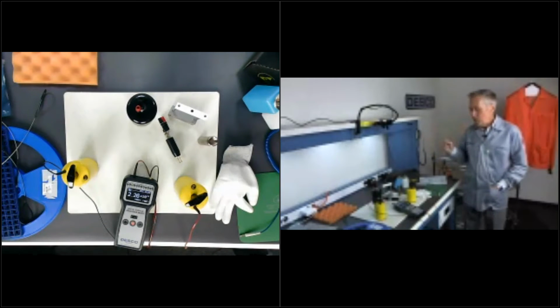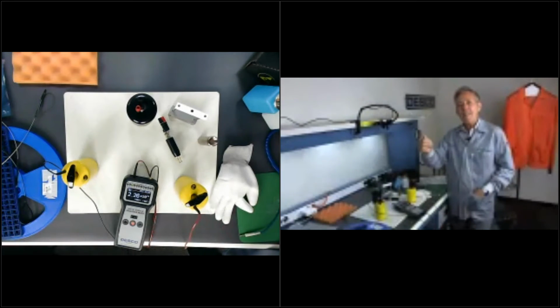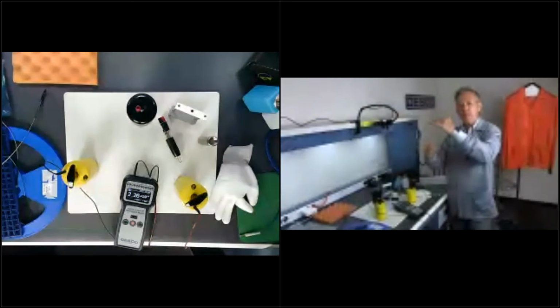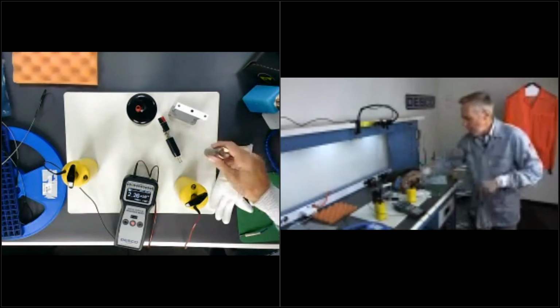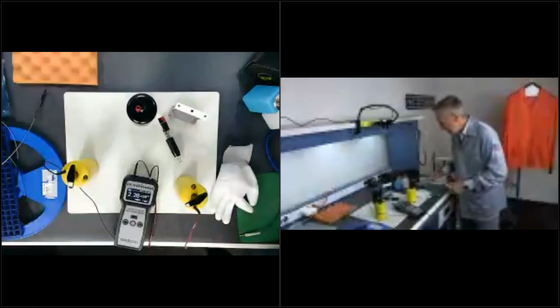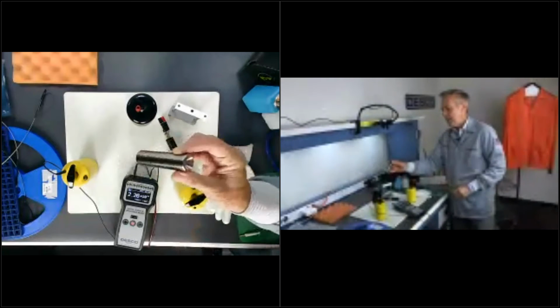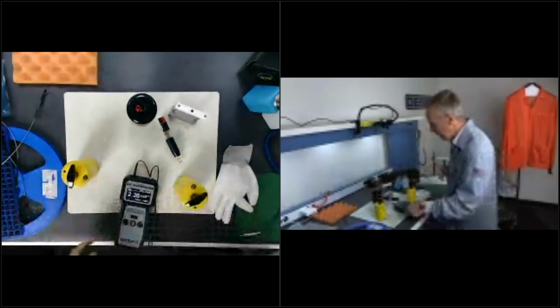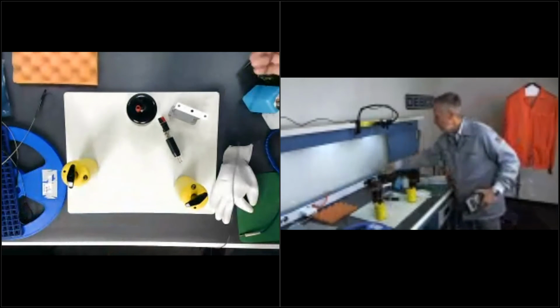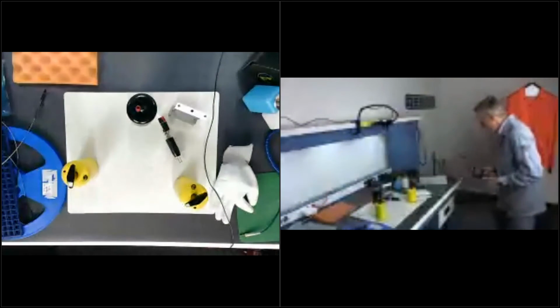When you stand on your footwear tester and you press that button, those limits are built into the tester. When I get a green pass, I'm under that number and I move on, I go to work. But if I actually want to know what my body's resistance is, I can use this little probe that we have here, and this complies to the requirements of TR53. And again, I'm going to take my black lead and plug into a ground point. Okay. Now I'm going to stand on my tester.